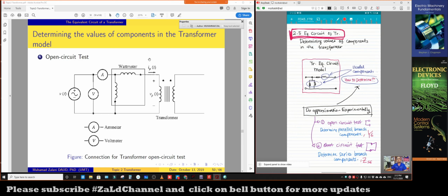Okay, so the open circuit test is basically based on this figure. We leave the terminal at the secondary side open. As you can see, there is no connection to load, no short or connection to load. We left it open like this.